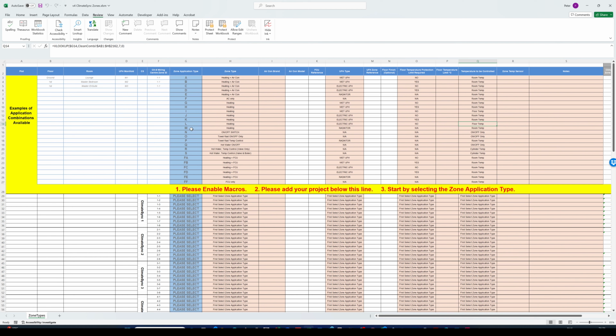Then type M will be a radiator, room temperature control, heating only. So that's without air conditioning. That's type M. Type N will be just an on-off switch. So here we have an on-off only. We're using it with no temperature control, just using it for on-off, if you want to use it from the wiring center, for example, to switch a fan on and off.